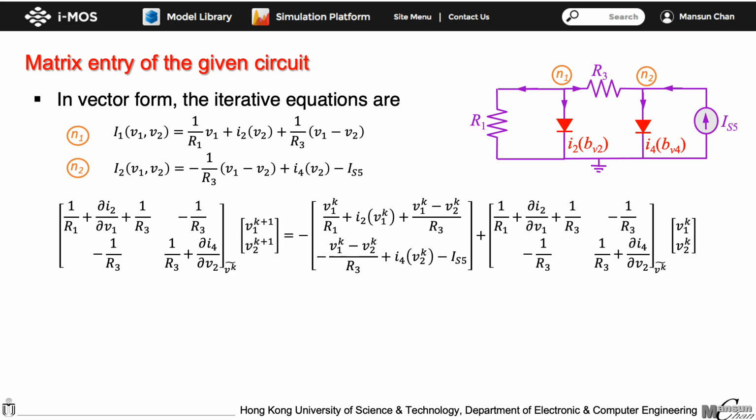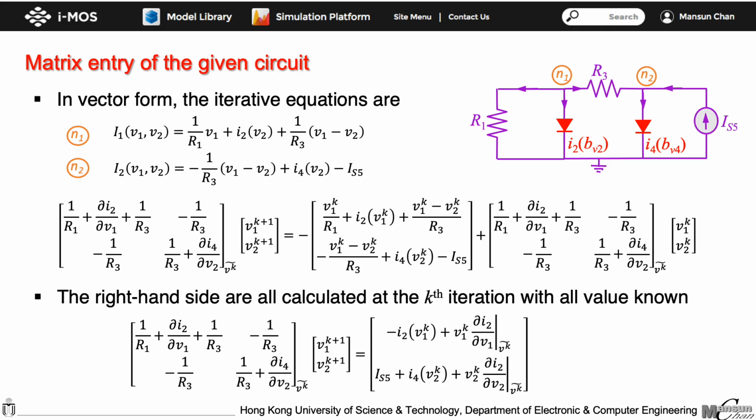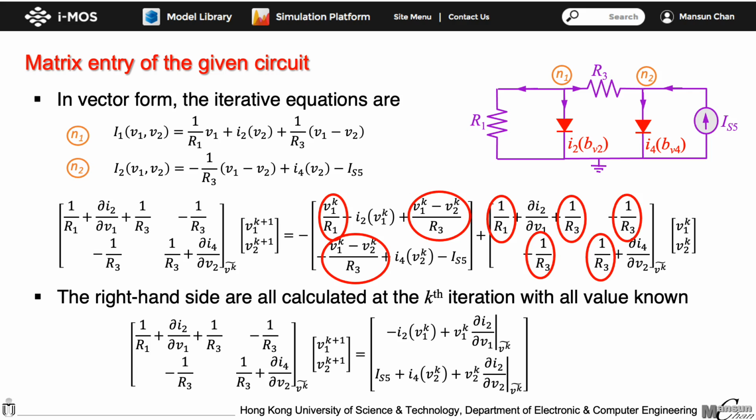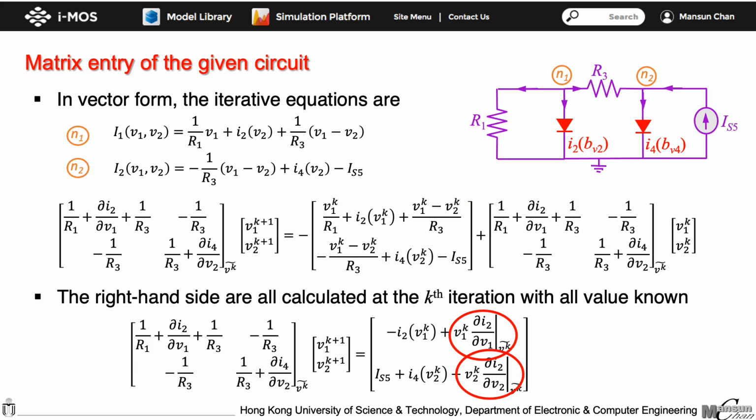Actually, many terms on the right-hand side of the equations cancel out each other, and it can be simplified to what is shown here. But we will generally refer to the form above it, because it is a more universal way to calculate the required values. It should be noted that all the terms from the linear elements disappeared on the right-hand side of the equations. It is also true for I2 and I4 if they are linear elements. In such a case, the equation expressed as voltage time derivatives is exactly the same as the first current term. So the two terms cancel out each other.